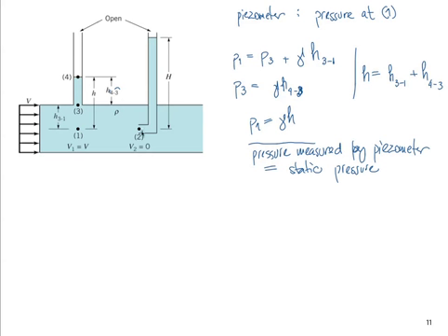Now, if I look at this other point here, point 2, just a couple more minutes, and we'll continue next class with applying Bernoulli's equation. Let me just point out that at point 2 we have a small tube that is bent, and the fluid goes in, and it has to come to a full stop because the fluid inside this little pipe is actually static.